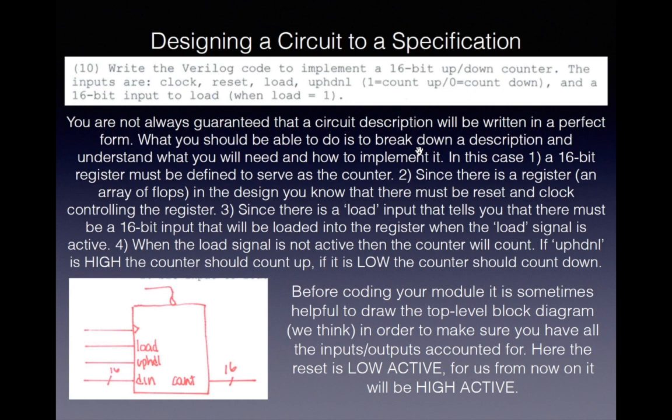Since it has a 16-bit counter, you know it's an array of flops, so you know there's going to be a synchronous device. It refers to a load. It refers to a 16-bit input to load. So before you start writing the Verilog, you should draw the top-level block diagram.